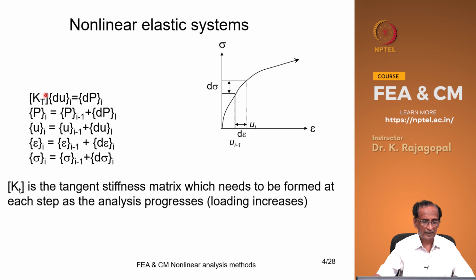And our K is now the tangent stiffness matrix, because with increasing stress or increasing strain, your slope is changing. So we update our constitutive matrix and then update our stiffness matrix, multiplied by incremental displacement is equal to incremental load corresponding to some incremental stress.